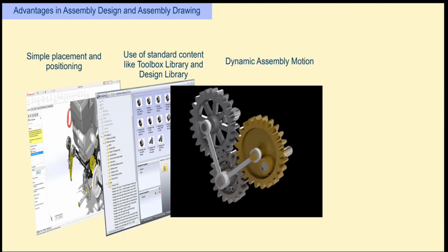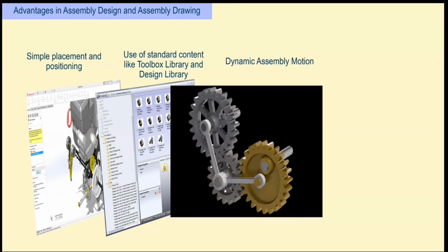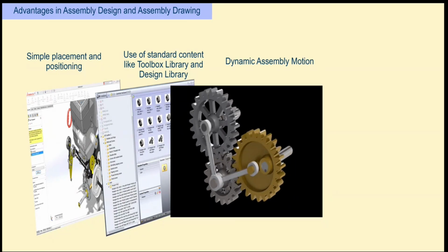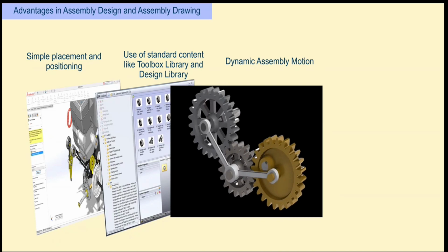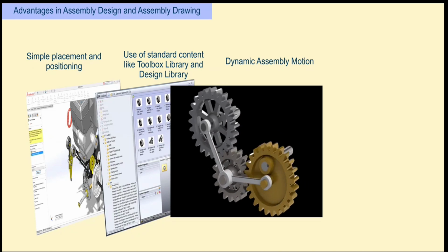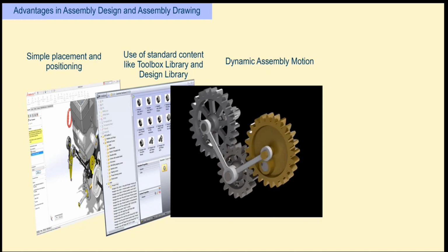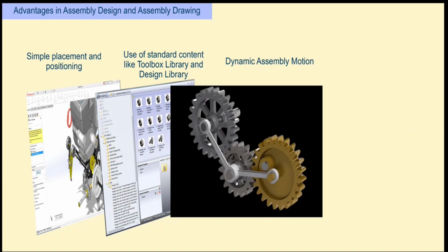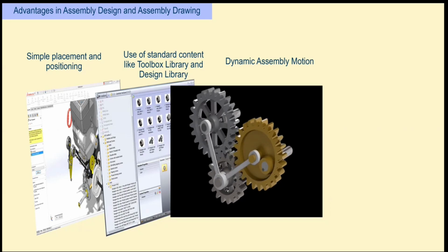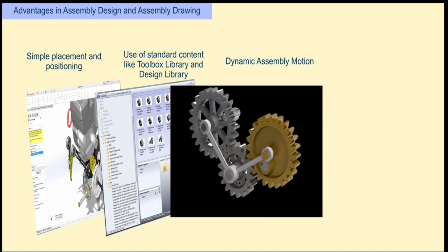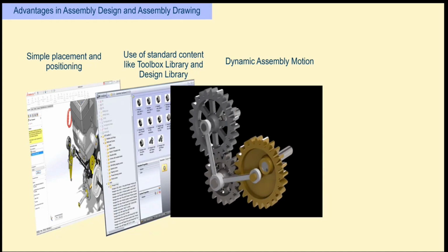And next, if you have any moving components in your assemblies, you are working with gears or shafts, and you need to create a perfect motion of it with respect to time. So you can do that seamlessly using SolidWorks Motion. You can create various plots of acceleration and velocities with respect to time, and evaluate where the component's reaction force is more, and ultimately evaluate the assembly.